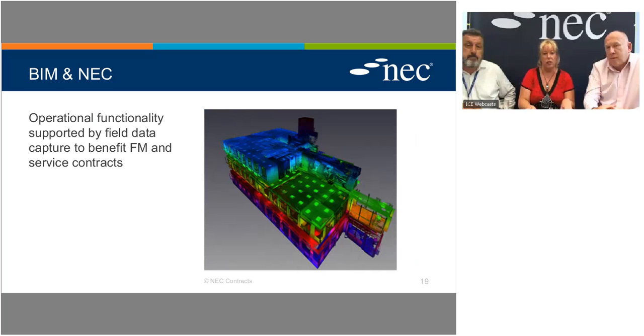And then operational functionality as well, supported by field data such as BIM 360, where the guys on site can go out with iPads with all the operational information loaded up. Particularly helpful on the NEC line, Rob, is that they can do all defect snagging by dropping pinpoints where they detect a snag, pick that up, then go back and demonstrate to the client that the defect's been rectified and managed out, making less issue on handover. I think that's where a big push is coming in now, with some of the big construction firms bringing this skill back in, and I can see huge benefits to that. Yeah, definitely.